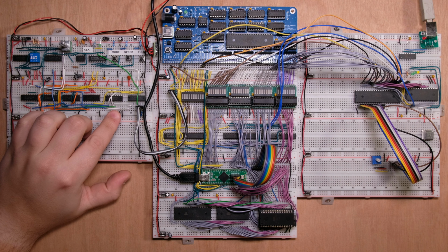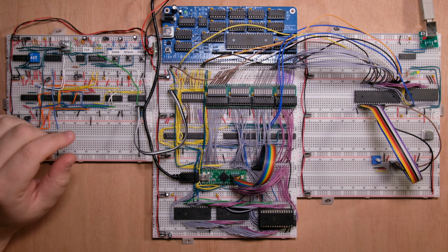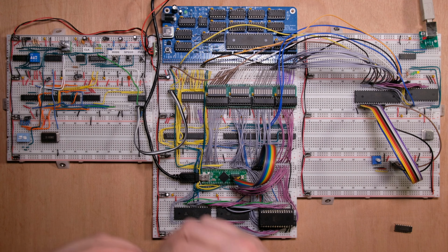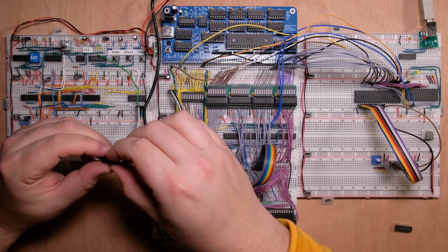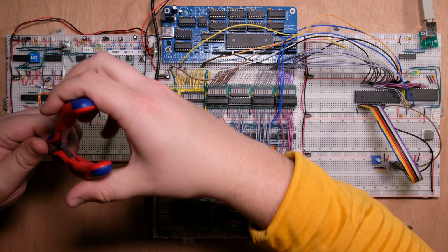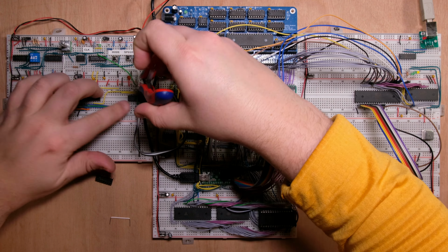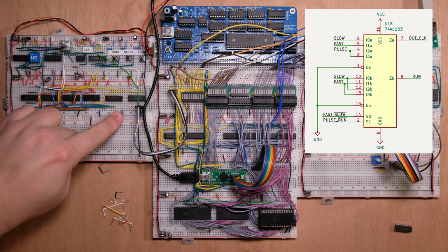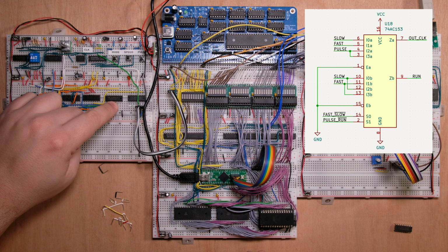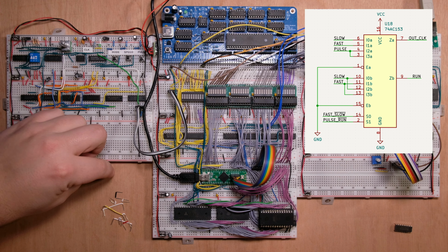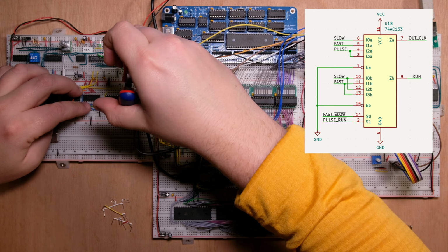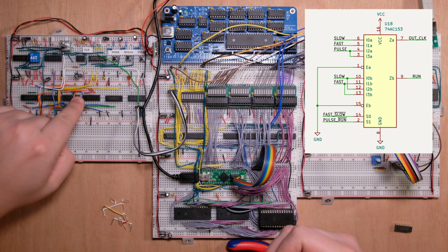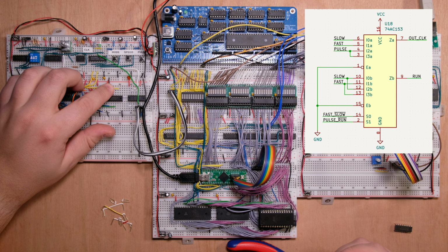Okay, so let's start by redoing the output stage. So we can remove the 74151 that we have in the circuit. And I have here the 153 that is going to be in the replacement. So let me first remove all the wires. So power and ground is already there. Then we need pin 1 and pin 15 pulled to ground. So this wire here is the fast and slow selection bit. And we need this to go to pin 14.